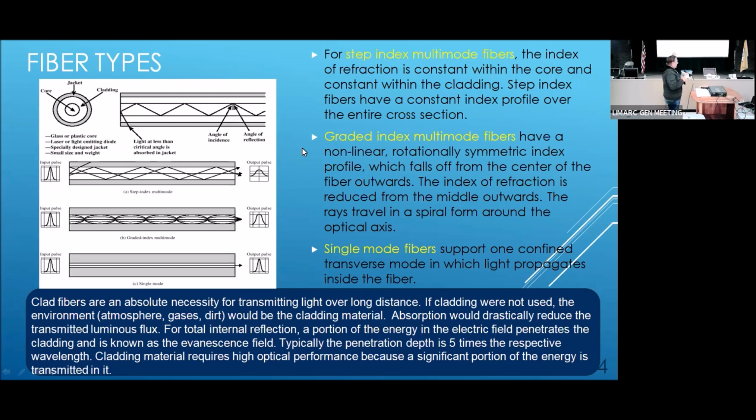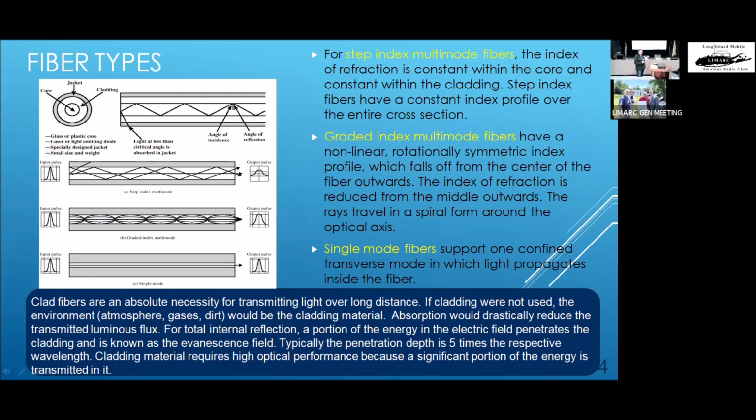Okay. And there are several different kinds of multi-mode fibers. One is called the step index, in which there's a solid boundary between the core and the cladding. That's great. It allows for a simplified system. It's somewhat cheaper to build. So the downside is that there's a lot of pulse distortion in that, and as a result, the data rate that you can get is pretty low.